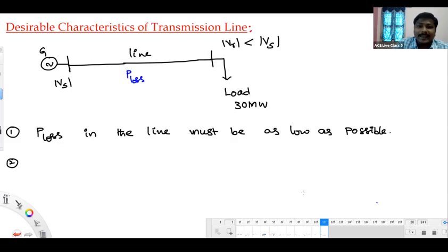Why is it less? Anybody tell me please. It is because of voltage drop, not because of power loss. Salman Khan and Imtiaz, it's not because of power loss. It is due to voltage drop in the transmission line. So we have some voltage drop in the line that is making the receiving end voltage magnitude less compared to the sending end voltage magnitude. Okay, done. Next.